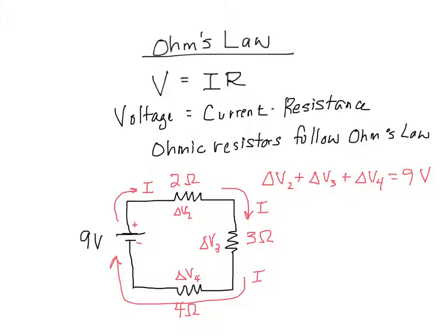That's kind of like what happens when you try to push too much charge, too much current through a wire that's not sized correctly. Also, in your house, you have circuit breakers that are designed to actually trip or break the circuit. So it basically is like a switch that disconnects the circuit when too much current is flowing through it. So it senses how much current is going through the circuit and trips and breaks the circuit so that the wires don't heat up and cause a fire.